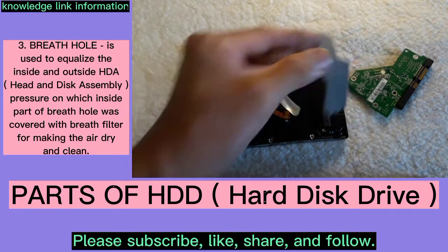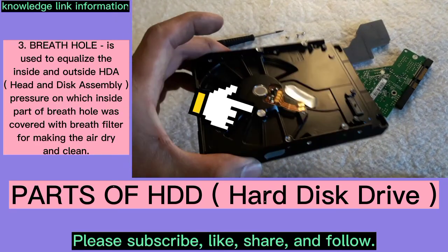Number 3. Breath hole is used to equalize the inside and outside HDA or head and disk assembly pressure, on which the inside part of the breath hole is covered with a breath filter for making the air dry and clean.